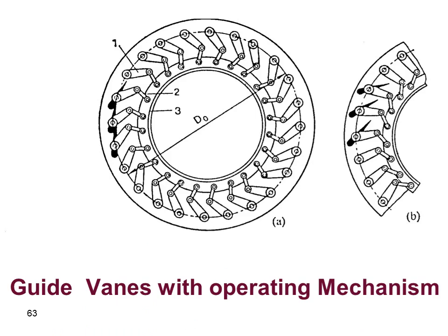How do they close or move the guide vanes, as we see in figure A or figure B? The same. We have the guide vanes colored in black, about 3 plates. We see three of them in black, connected through some links to number 3, which is a rotating ring, or we call it the control ring.